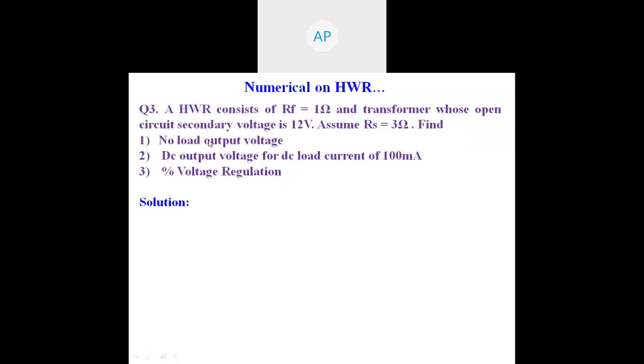What is the no load voltage for a half-wave rectifier? It is given as VNL equal to Vm divided by pi. Can you find the Vm here?